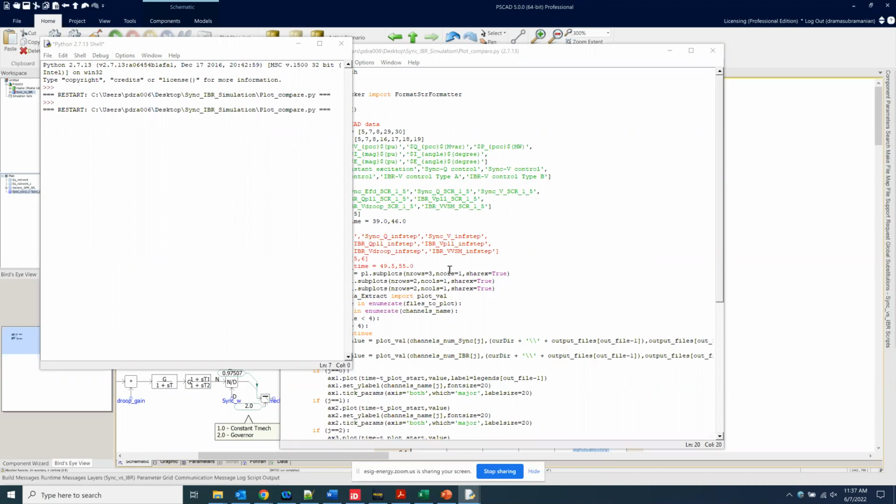But that controller is slow. What the plant controller does is it sends active power commands and reactive power commands down to each inverter. So at the inverter level, each inverter is operating on closed loop active power control and closed loop reactive power control.